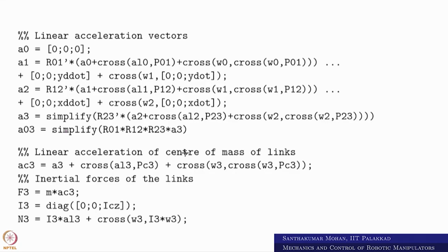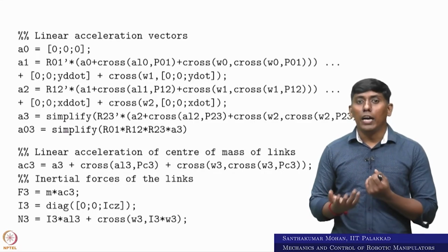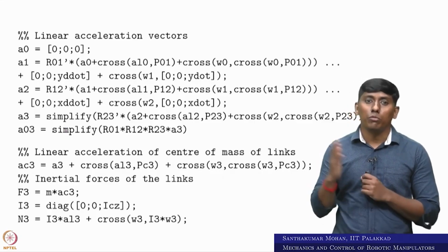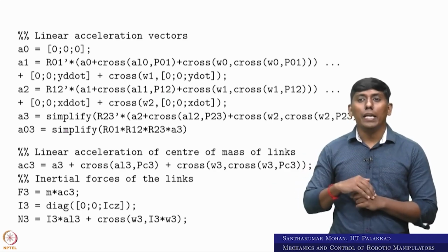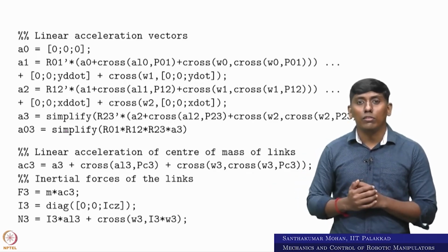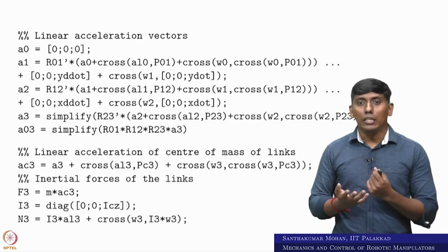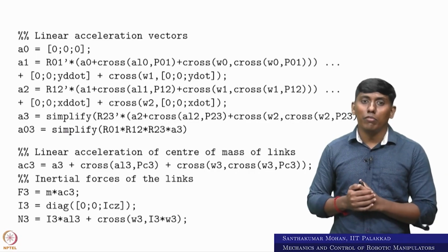The initial effects you need to actually come back. So here you have initial force and initial moments, right. So what are the initial force and moments? F3, which is M3 multiplied with the AC3, where M3 here is only one body, which is just M, and here we assume that it is in a plane. So in that sense, it has only the centroidal moment of inertia, that too about the z axis only, the second moment of inertia. The product of inertia we assume to be 0. So then you can see the initial moment we can calculate.